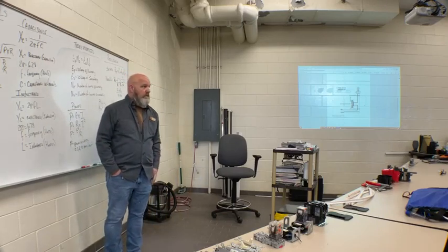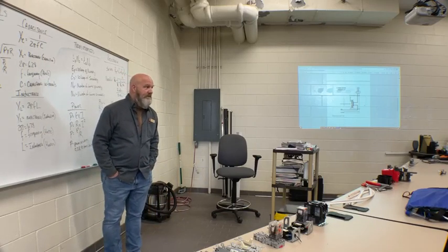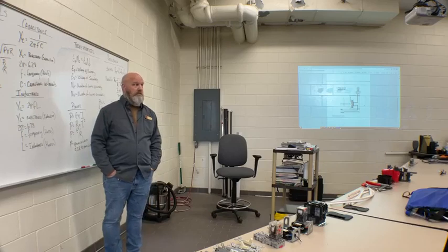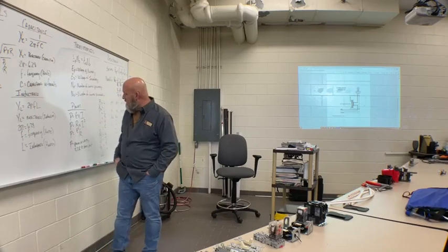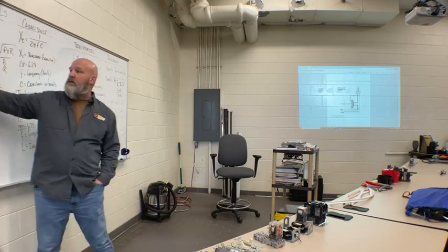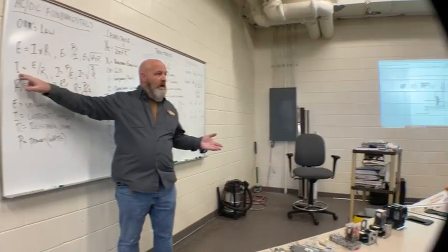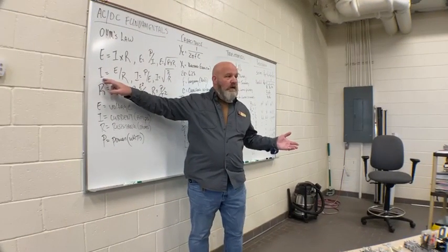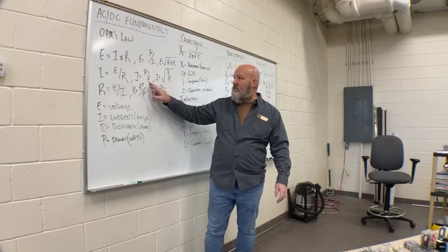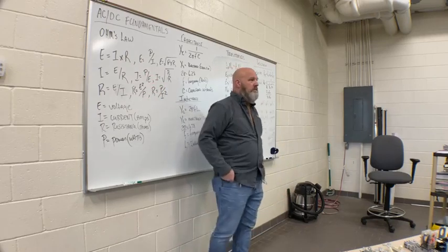I don't know. Well, how many amps is it going to draw? Well, if I want to know current, I know my 4,500 watt hot water heater runs off 240. I take the power, divide it by 240, that gives me my current.